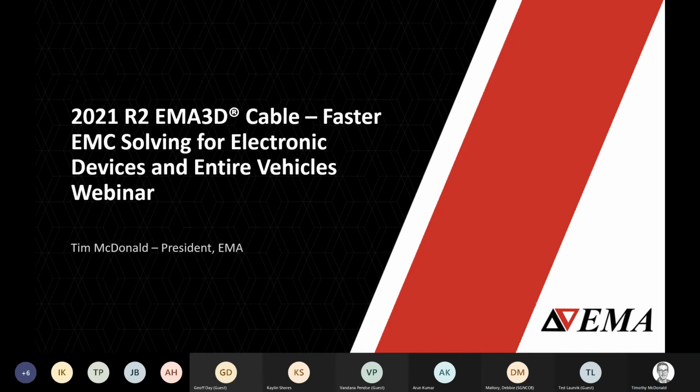All right, next question is, is it possible to simulate full electronics enclosures and their PCBs with EMA3D Cable? If so, how long does it take to build such a model? Sure. So we showed an example of the Galileo board earlier in this presentation, where SIwave was used to model the entire electronics package that included a processor, 2 RAM modules, as well as about 16 individual nets of that circuit.